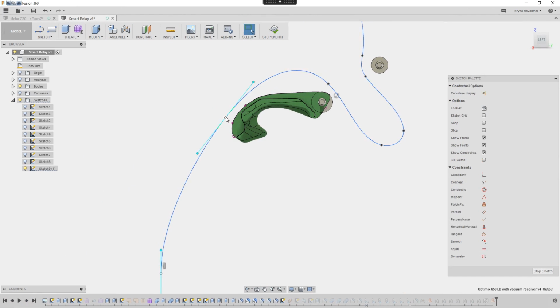Next, when you select the spline, different handles pop up at spline fit points and endpoints. These handles control the tangency vector at that point. With these handles, you can control the magnitude, which is the length of the tangency handle, and the angle or direction it's facing. We can also activate the curvature handle at these points.